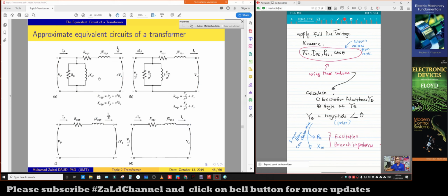For the transformer, which is something like this, in the open circuit test we are going to measure the components RC and XM. There is nothing to do about the series components, REQ and XEQ here, because the series components we determine by using the short circuit test.